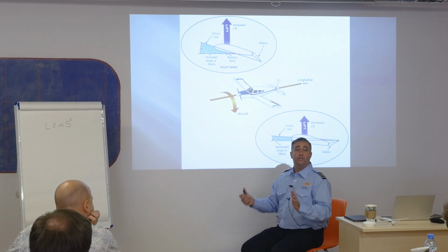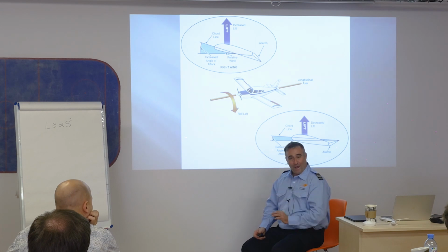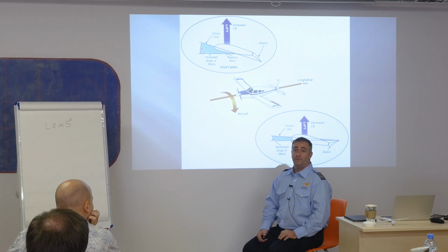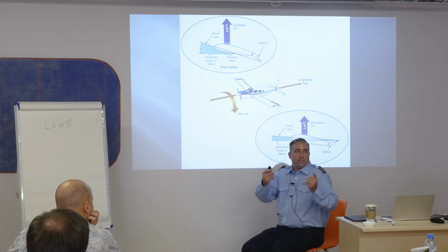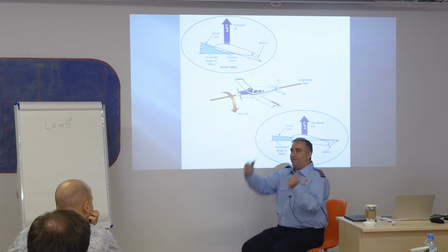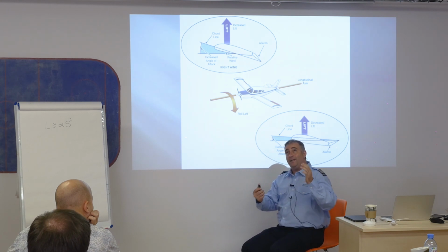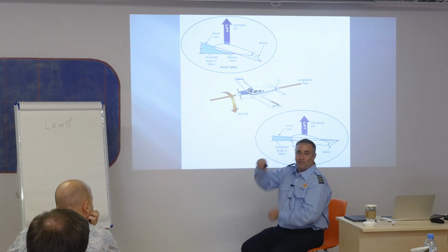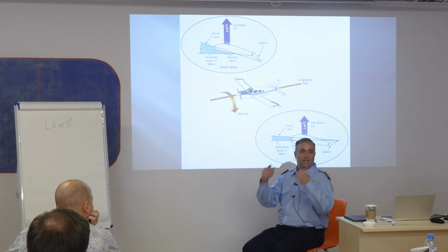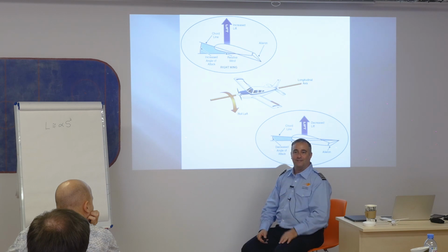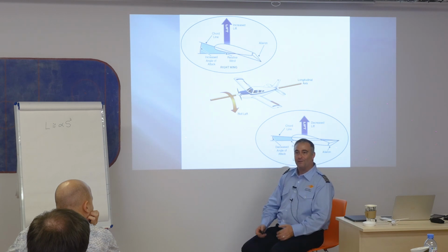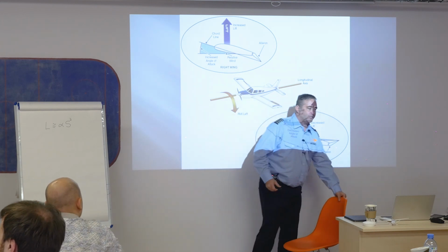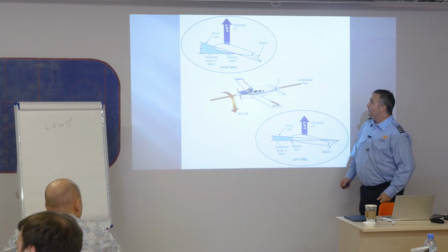But the adverse yaw is a very, very important concept, and so many times is confused because, shoot, I just got in this machine. You know, I wanted to turn left, and this looked like a good way to do it. I get you, but every time you turn it to the left, it's yawing to the right. And then when you straighten up your controls, it's coming back down. Now you're telling me you can't control the altitude. Well, there's a reason why you can't control the altitude. You're not using coordinated controls. All right? So important that we're using the coordinated controls there.